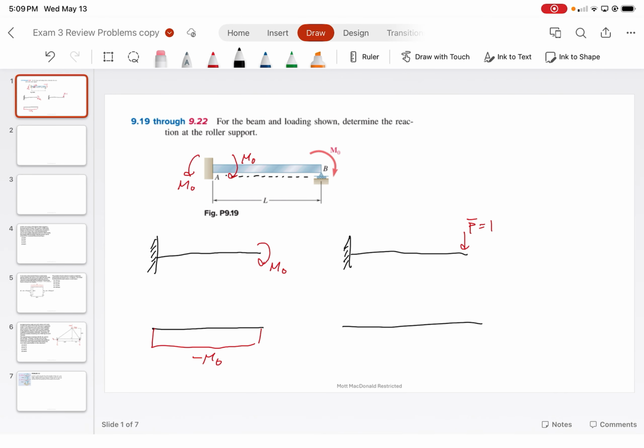Now, similarly, this is going to result in negative bending, but the bending moment diagram, because it's a point load that's applied, is going to be linear like that. Now, both of these are length L. They're both negative. So this is just going to end up being negative L for the bending moment, or negative 1 times L. All right, but what we need is technically this m of x. What is m of x? X goes this way.